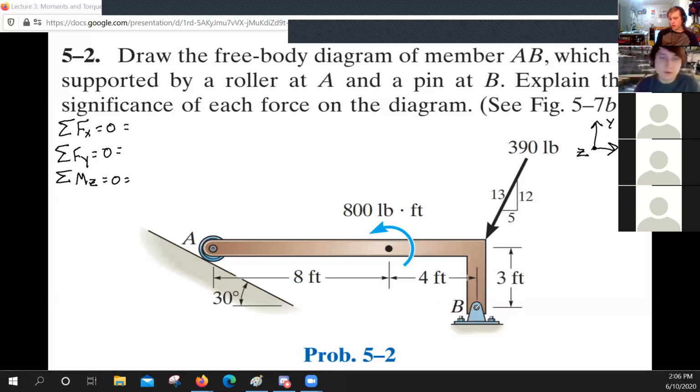Okay. How about Alex? You want to? Yeah, what about normal forces? Yeah, so there'd be a normal force, which, because this is a joint, like a pin joint, we're just going to call it F. We're just going to call it a force. But yes, there would be a normal force coming from B. And what we'll call that is F of B of Y. I know that's a little weird, but it is a force that is on B, and it is in the Y direction. Okay.